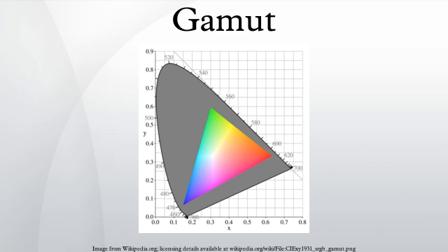Digital light processing, or DLP, technology is a trademark technology from Texas Instruments. The DLP chip contains a rectangular array of up to 2 million hinge-mounted microscopic mirrors. Each of the micromirrors measures less than 1/5 the width of a human hair. A DLP chip's micromirrors tilt either toward the light source in a DLP projection system or away from it. This creates a light or dark pixel on the projection surface. Current DLP projectors use a quickly rotating wheel with transparent colored pie slices to present each color frame successively. One rotation shows the complete image.